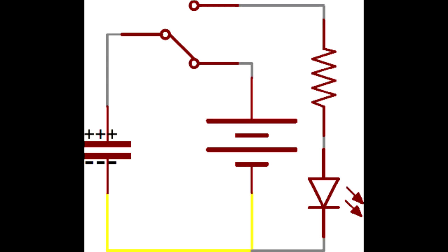For example, in this circuit, a battery can be used to induce an electric potential across the capacitor. This will cause equal but opposite charges to build up on each of the plates, until they're so full they repel any more current from flowing. An LED placed in series with the cap could provide a path for the current, and the energy stored in the capacitor could be used to briefly illuminate the LED.